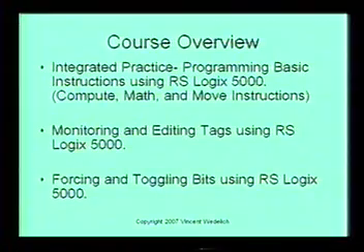Then we'll get into programming basic instructions using RSLogix 5000, compute, math, move instructions. Then we'll touch again on monitoring and editing tags using RSLogix 5000. Then we'll go into forcing and toggling bits using RSLogix 5000. Some of these ideas you've probably seen me do as I go along. I'll toggle a bit or force something on, or I'll start monitoring a tag. But we'll talk a little bit more about it and play with it a little bit more.